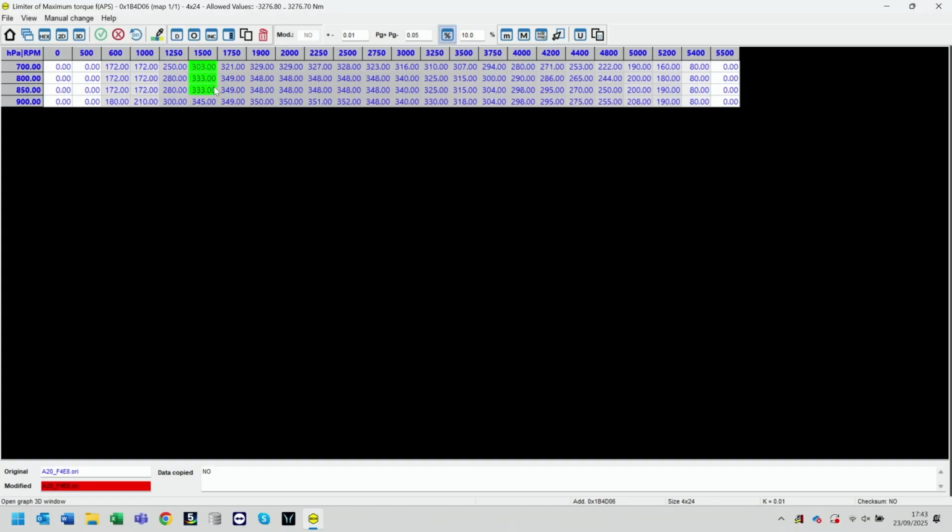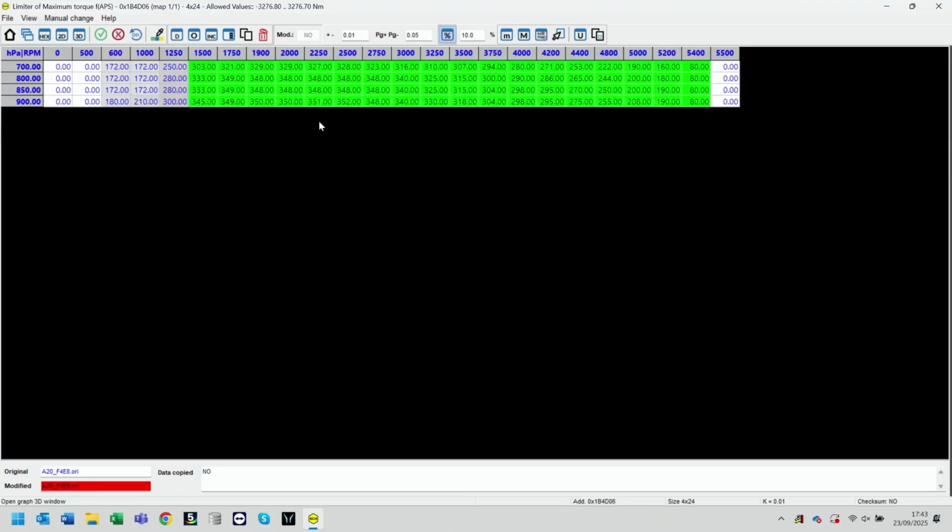So the typical areas we're going to modify, I'm just going to highlight them on the screen, is this area. From approximately 1500 RPM, which is typically where boost starts to really spool on the car, the vehicle's out of that operating condition of the initial starting or changing gear, that initial inertia break point. Away from that point, the vehicle's starting to accelerate up. This is where we need to make our modifications.